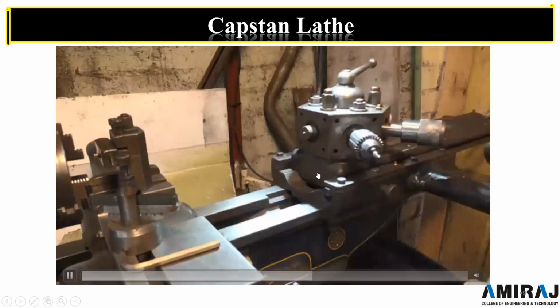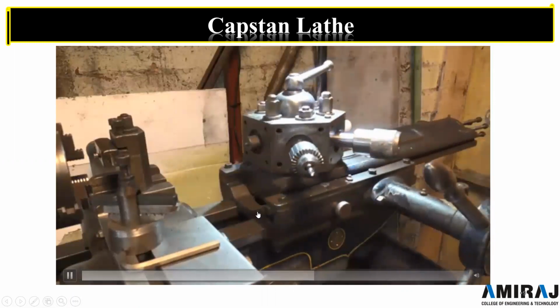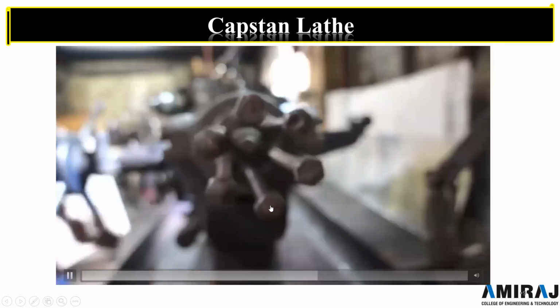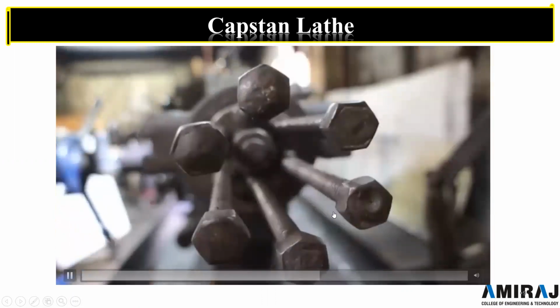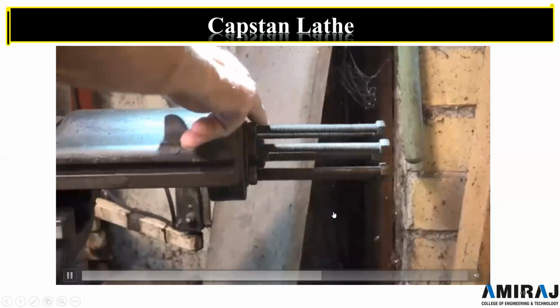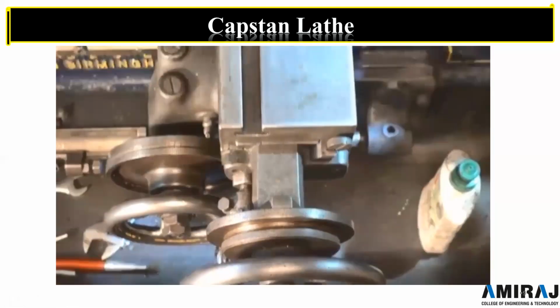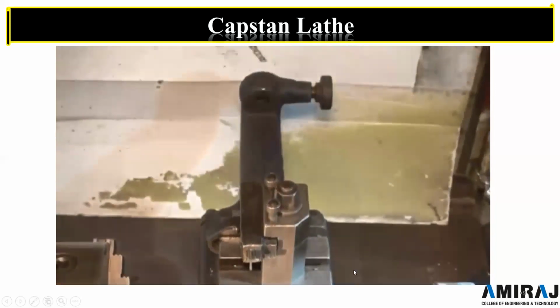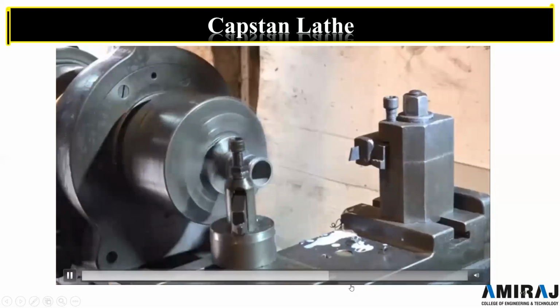The turret saddle can be positioned anywhere along the bed, and each of the 6 positions of the turret has an adjustable threaded stop that controls the distance the auxiliary slide can plunge. The cross slide carries a turning tool and a parting tool. This is the tool that parts off from the rear. This reduces the chatter and the possibility of the parting tool digging in.